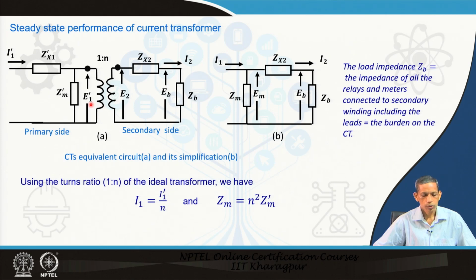So, with this the current is input to the primary, which is the system conductor, the transmission line conductor or transformer conductor also. In that the corresponding current flows. Note one point here: for the CT, the current input to the primary is the conductor current of the system, and it does not depend upon the CT burden.